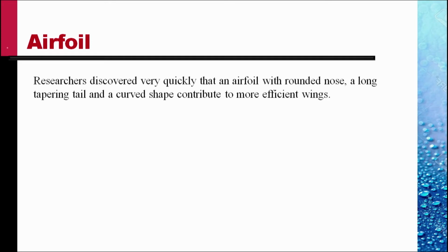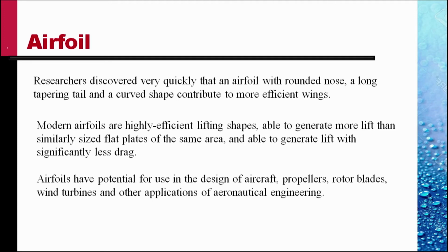Researchers discovered very quickly that an aerofoil with a rounded nose, a long tapering tail, and a curved shape contributes to more efficient wings. Modern aerofoils are highly efficient lifting surfaces, able to generate more lift than similarly sized flat plates of the same area, and able to generate lift with significantly less drag. Aerofoils have potential for use in the design of aircraft, propellers, rotor blades, wind turbines, hydrofoils, and other applications of aeronautical engineering.